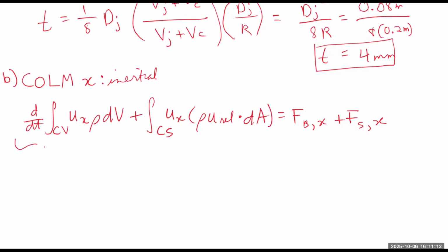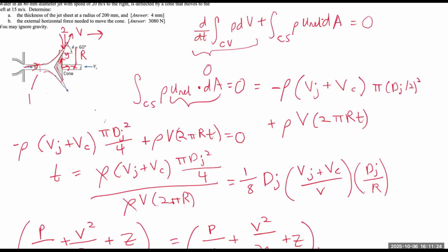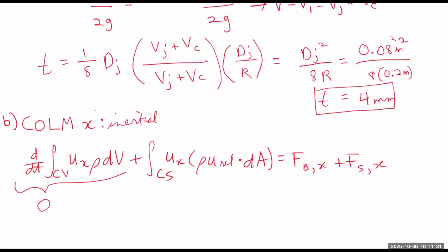And thus, this one is still steady state, because what this is saying is that relative to the control volume, is the mass in the control volume changing with time, or is the volume changing with time? And the answer is no, because what comes in goes out. However, we will have a non-zero for this term because it determines which volume goes in and which goes out.